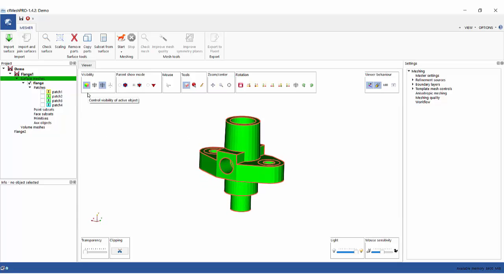The child nodes of a surface mesh are patches, point subsets, face subsets, primitives, and auxiliary objects. How any of these elements are properly applied in preparing a surface mesh for the meshing procedure is a topic of subsequent tutorials, and here we will mention only the basic information about them. Patches are probably the single most important surface and volume mesh topology elements. In our example, there are 4 patches named Patch 1 to Patch 4.